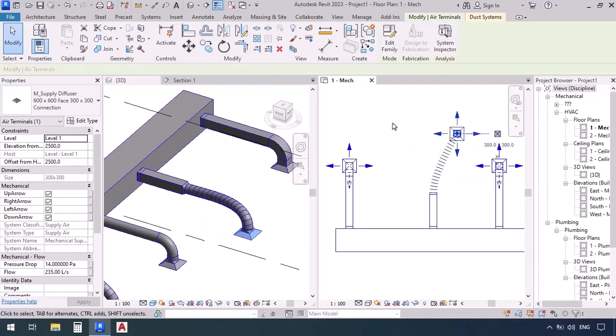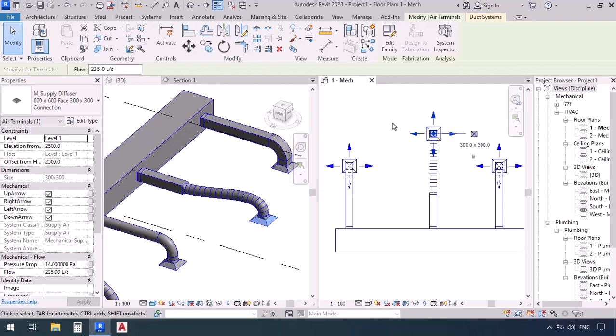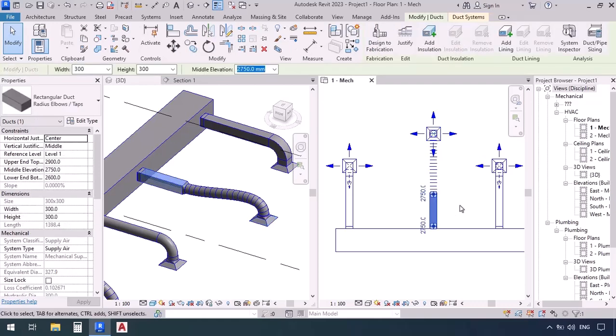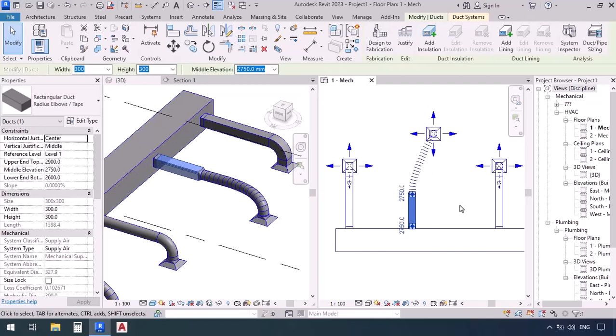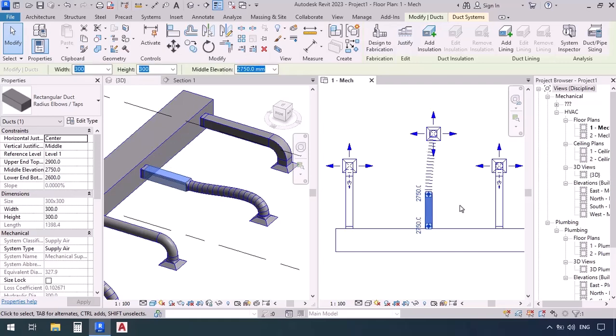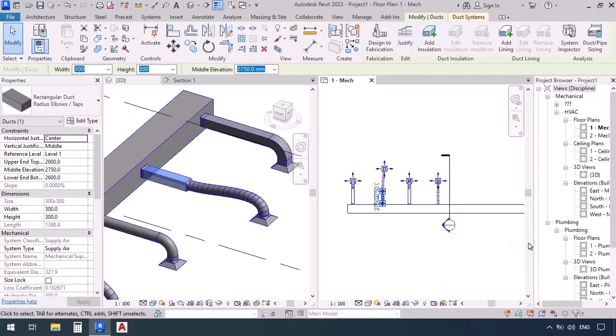We can also move it to the front and we can see the same thing again. Also to the left. But if we select the straight duct and move it to the right or left, you can see that the flexible extends again. I just want you to take in how this flexible duct works. It's completely flexible, it can take different shapes and moves in different ways.